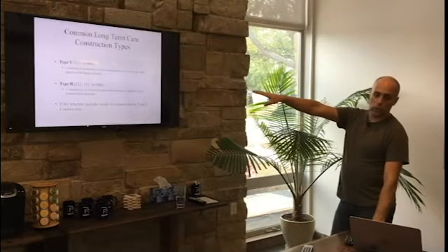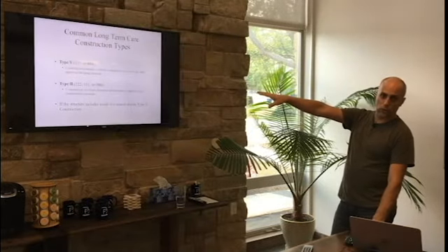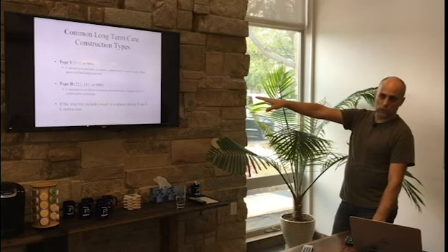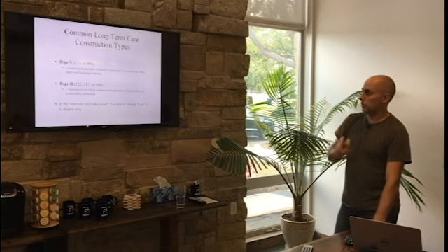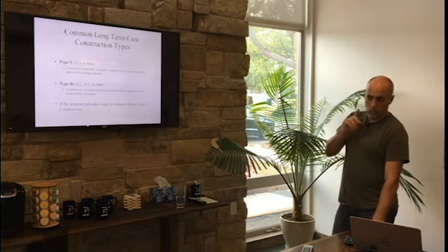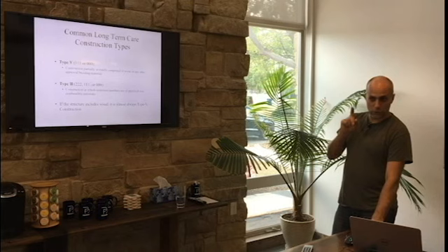And so you'll have no wood construction whatsoever in a type 2 under the 2000 edition of the Life Safety Code. In the 2012, there is one small little change, and I'll mention that. But as a company, we don't do it because it's too confusing.